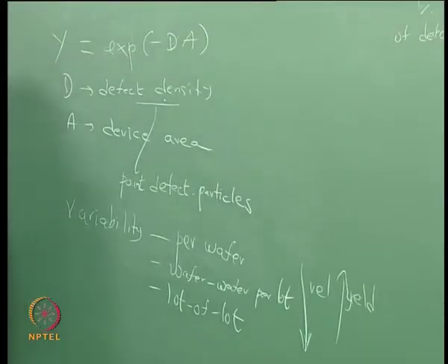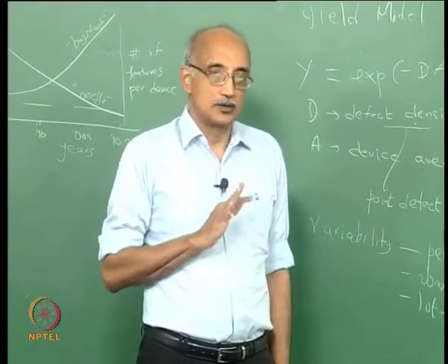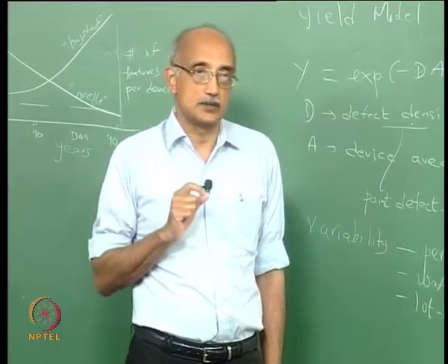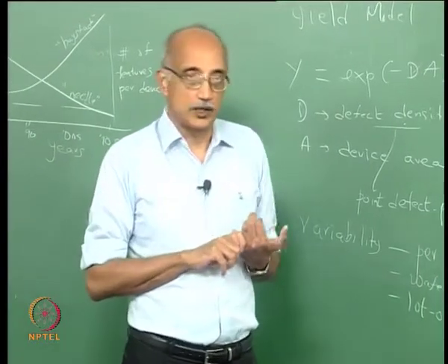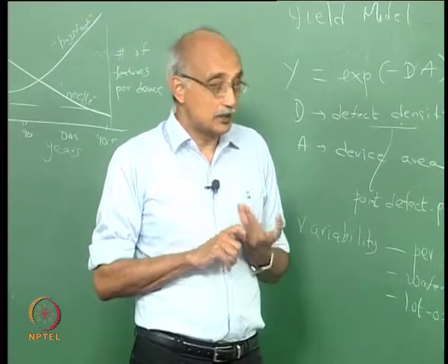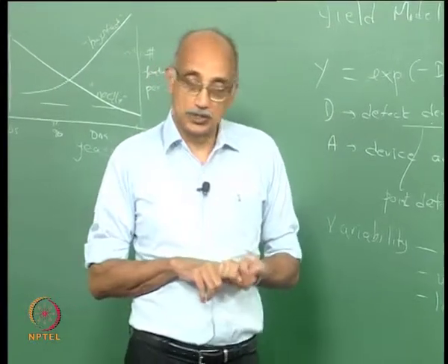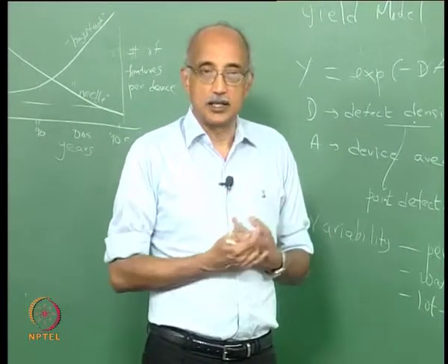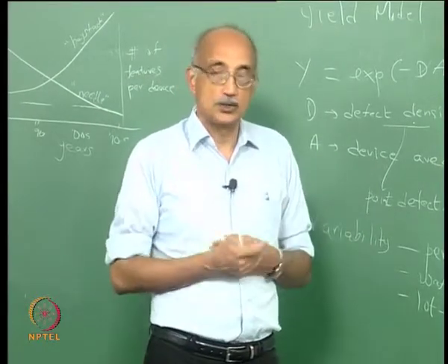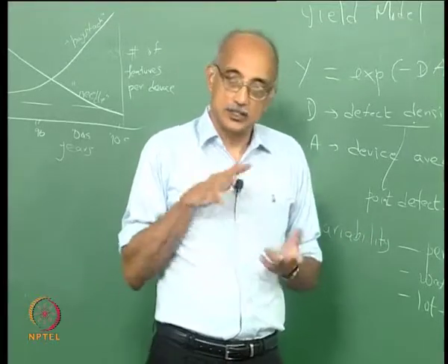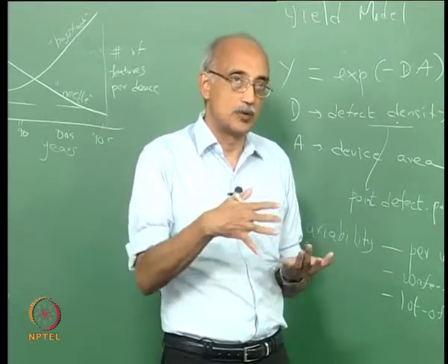Again, the reason why particle characterization is important is because during the design phase itself, you have to assess your product for its particle sensitivities and decide what type of particles are going to cause harm to this product, what is going to be the size range that is going to be particularly dangerous for this product, what is going to be the shape of particle that is going to cause damage the most, what type of chemical reactivities can exist, and you design your manufacturing environment, you design your tools, you design your product, you design your process in such a way that you minimize these specific types of particles that can cause harm to the product.